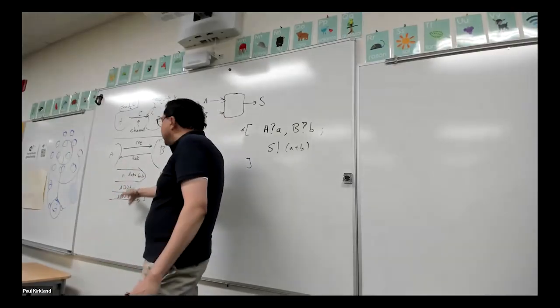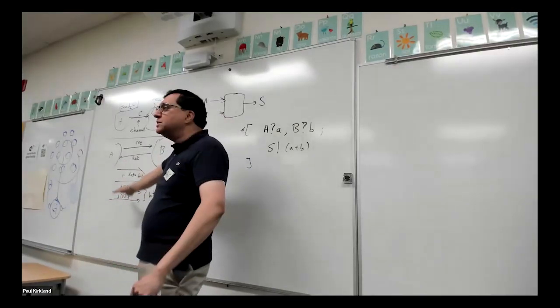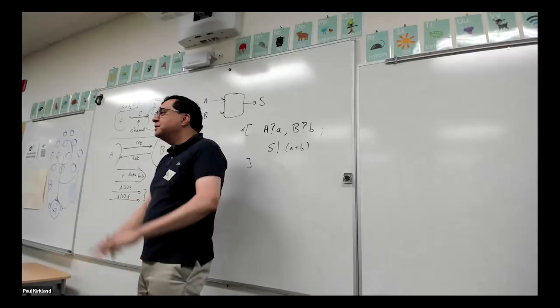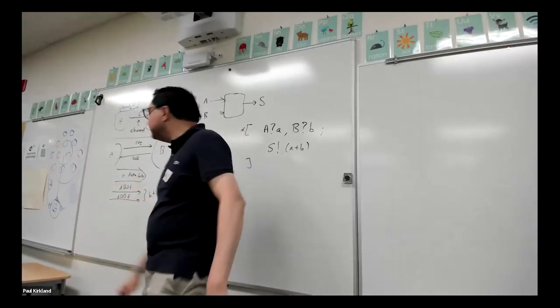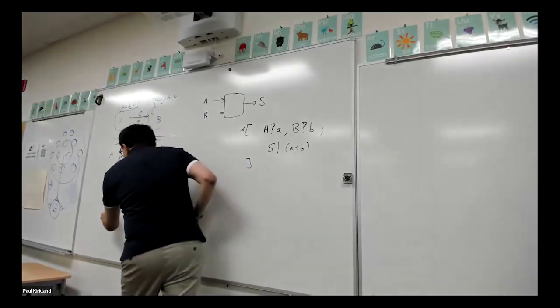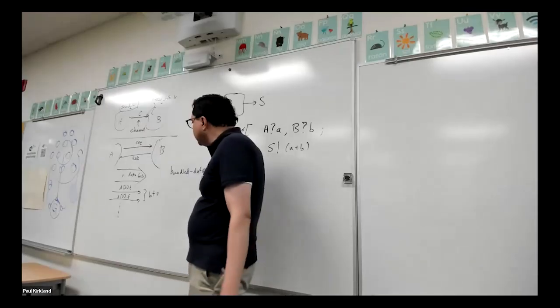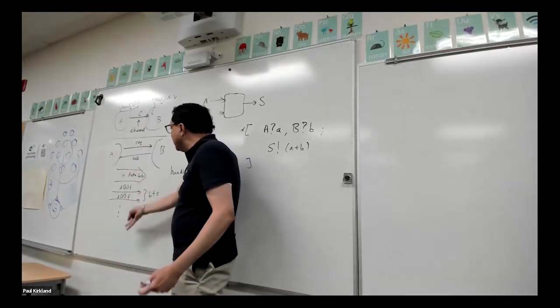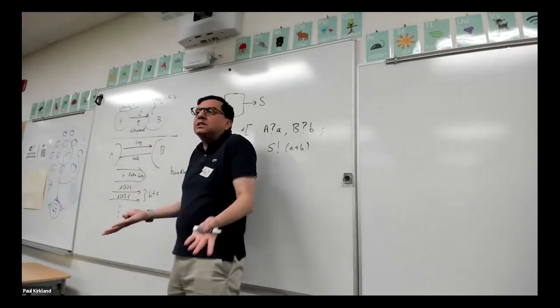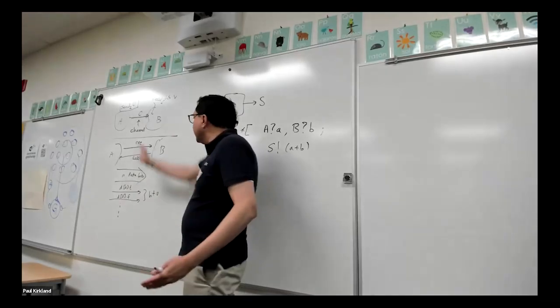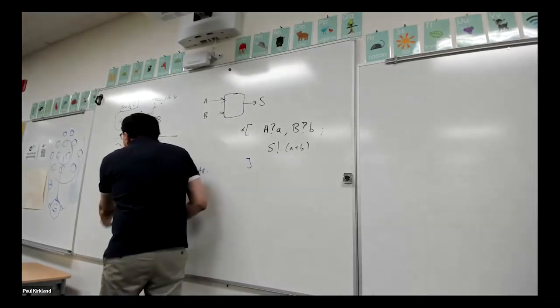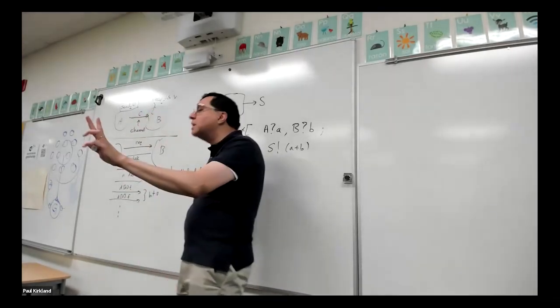By the way, where does this come from? 1950s information theory, delay insensitive coding. There are books on this. And I just have a bunch of parallel things like this, so this has 2N wires. But the other thing is I can use that as my request as well. So I can get rid of the request, but I have 2N data wires plus an ACK. That's 2N plus 1 wires for N bits.